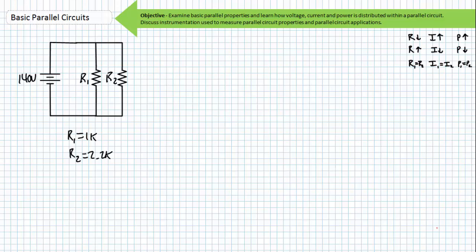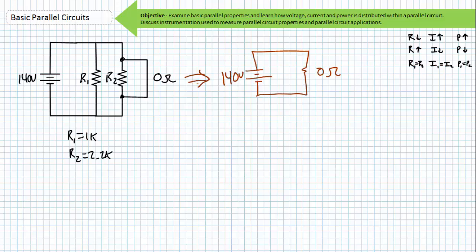A short is a 0 ohm resistance. If a short is placed in parallel with a single element inside a parallel relationship, in fact that whole parallel relationship is removed from consideration by becoming a 0 ohm path. This is to be generally avoided because a circuit with 0 ohms of resistance presents no opposition to the source, and current will spike to great magnitudes.